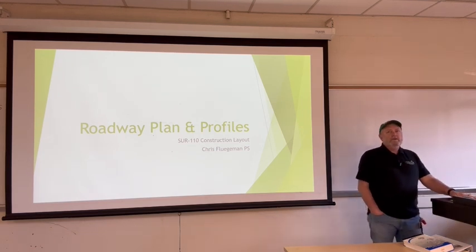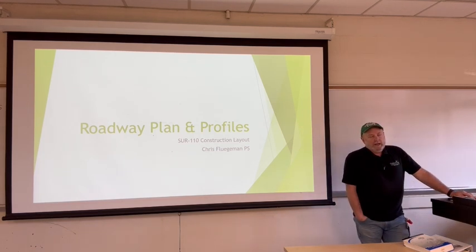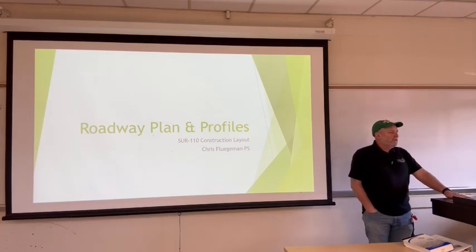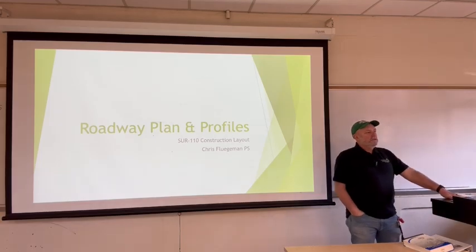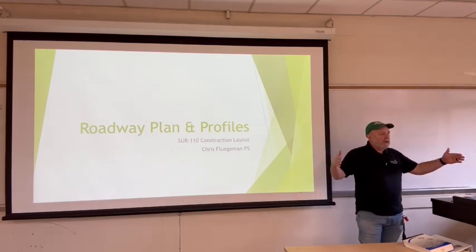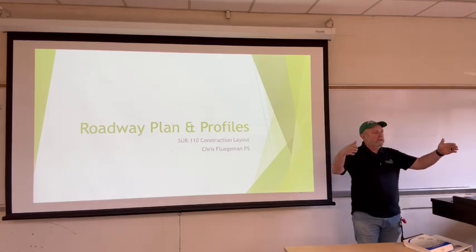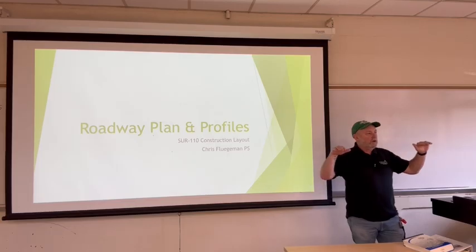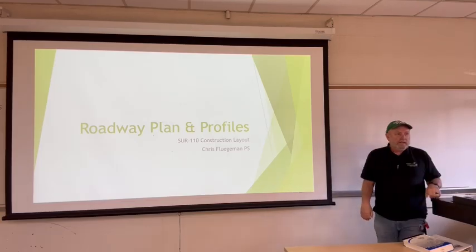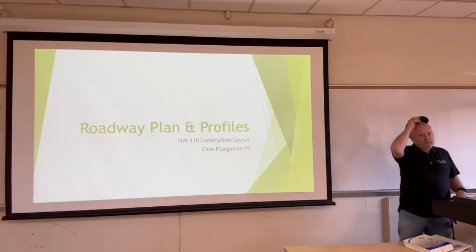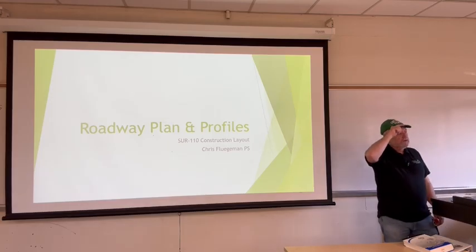What we will have is a roadway. Say it's 24 feet wide, a standard subdivision roadway, and we'll stake out a 3 foot offset back of curb, and we will grade those offsets to a top of curb elevation. That's going to be the plan. And again, this will take a couple weeks to do.